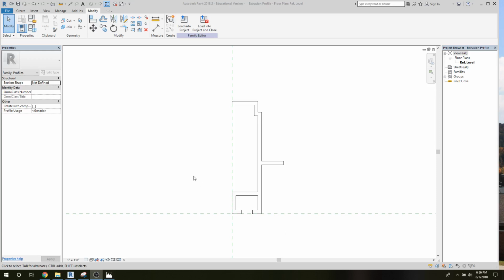Okay, this is going to be my actually second take on this extrusion profile. I had an error when I moved it into the other file because there were two lines overlapping, and this is a common problem when you make profiles, especially when you're manipulating a lot of shapes. Sometimes you'll have one line hidden over another, and when you import it in to do extrusions or sweeps, it'll error out, and it doesn't immediately become clear what the problem is.